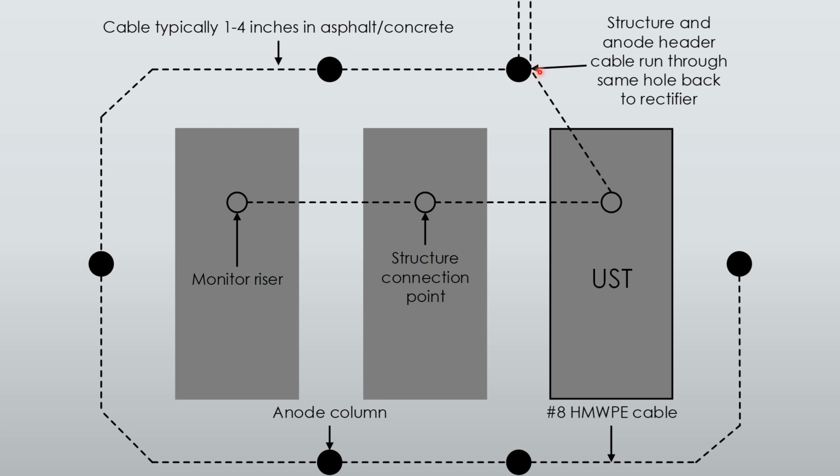Again, assuming well distributed. Some systems require 2 anodes on the sides of the tank wall. If you want to be a champ, you can put 3. Again, that will increase your excavation costs, but more is better in this case because you're trying to distribute your current more efficiently. The better current distribution we have, the more even our polarization is around our tanks.